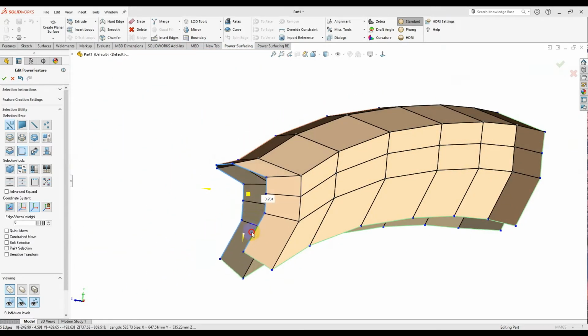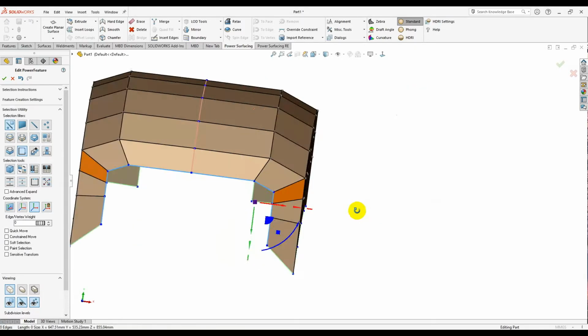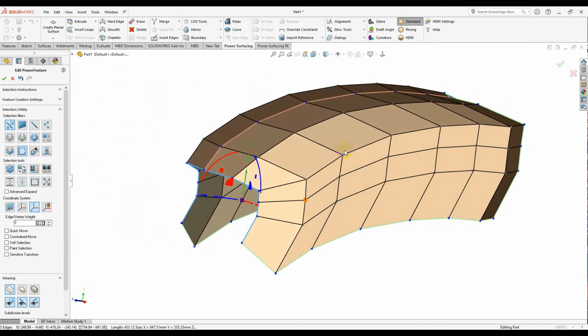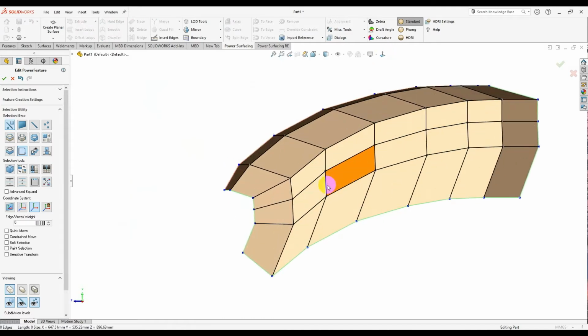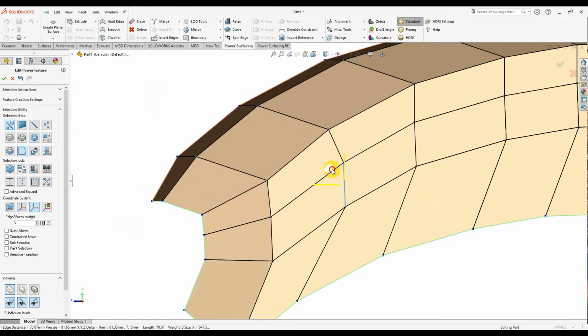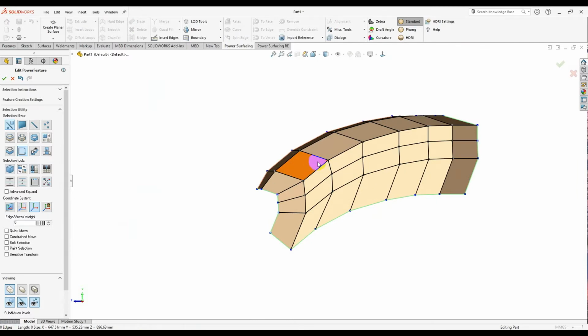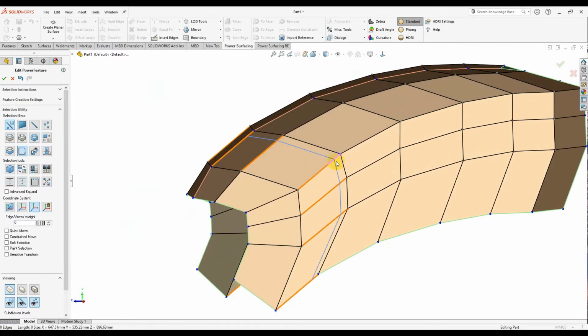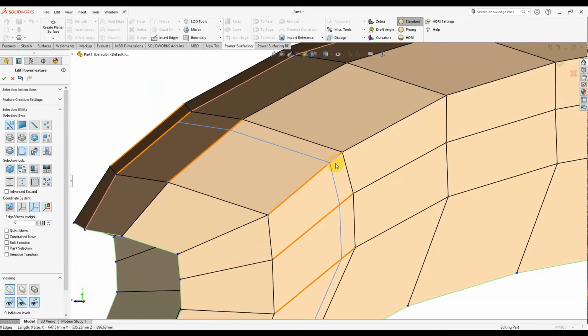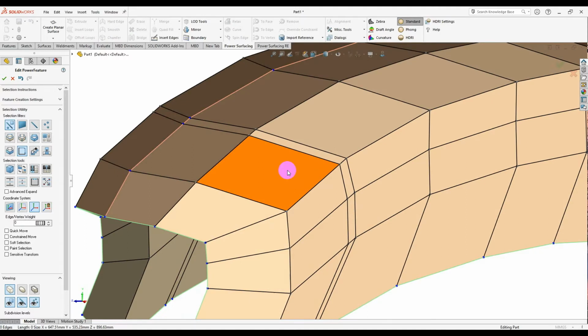Let's use the scale on the gizmo to give this nice shape from the back. So I'm going to move this from here, and create an edge loop here, pressing the A key, and select one like this. Now it's going to put the line here.